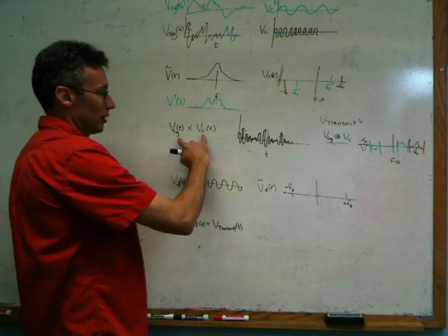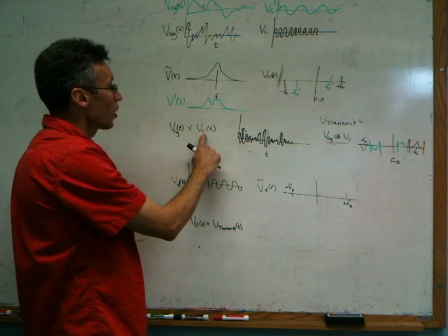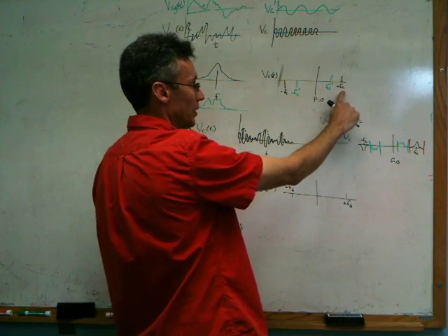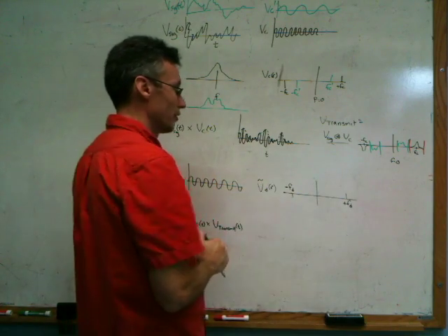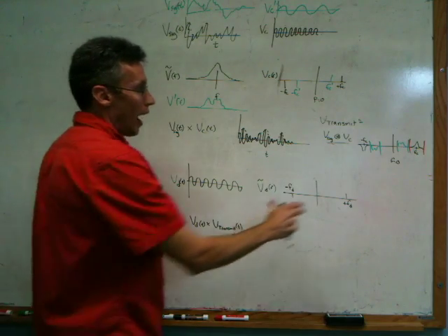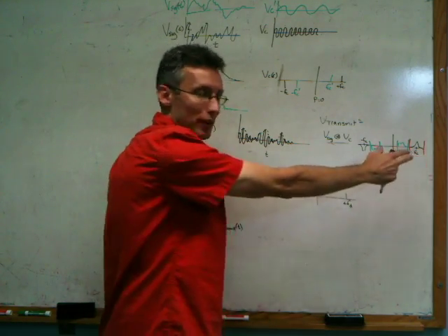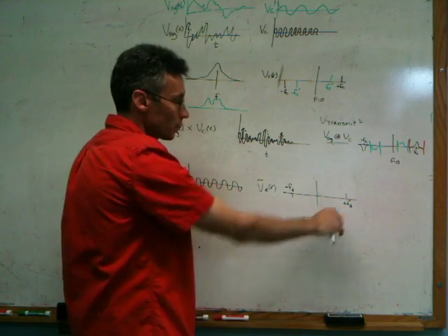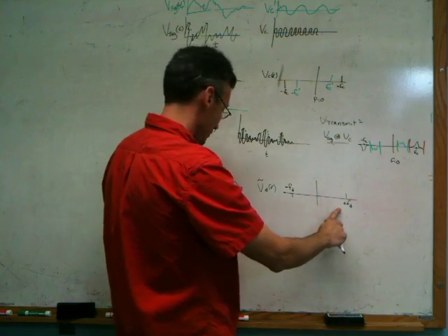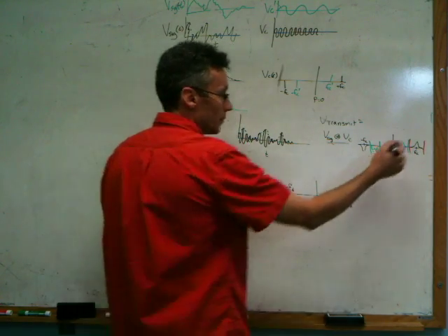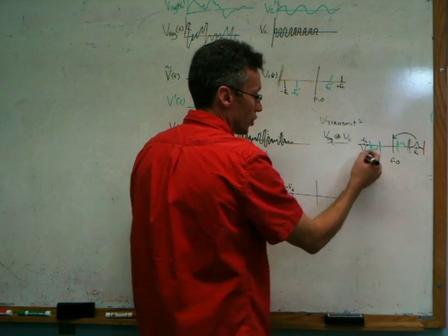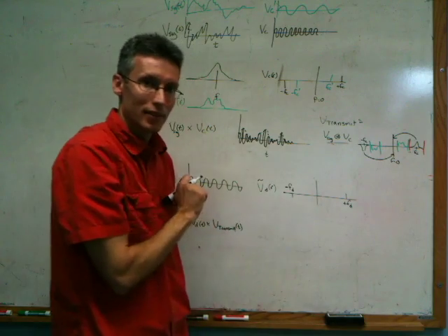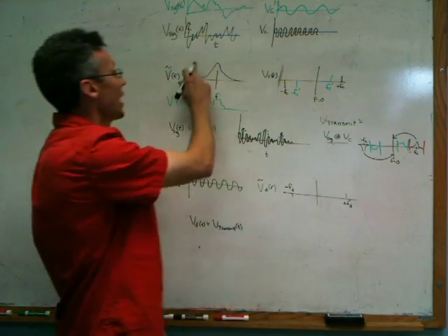And so just like the process of multiplication by a carrier up here caused the frequency component of our signal to get shifted by the carrier frequency when we did this convolution in the frequency space, now our transmitted signal is going to have its frequency spectrum shifted by the frequency of the demodulation. And so if we choose the frequency of the demodulation correctly, then we can shift the components that are centered in one channel back to DC, okay, back to the center frequency that they originally had before they were modulated.